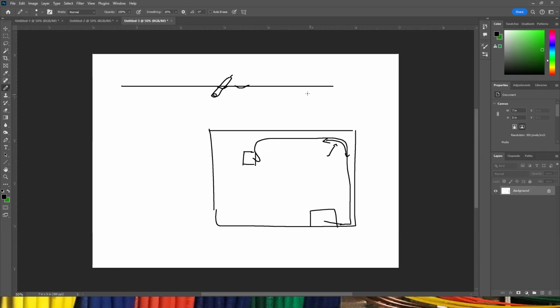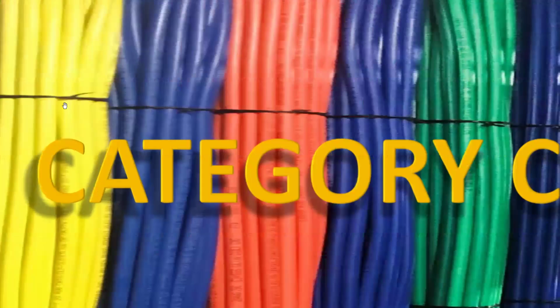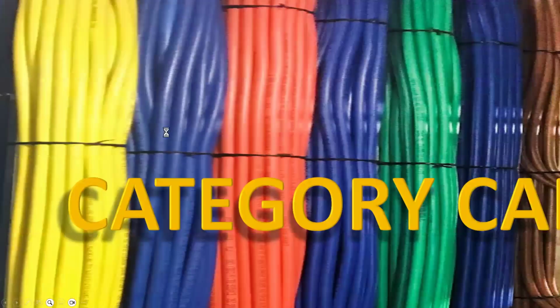Micro bends could be anything, could be a cable pressing on another cable. For example, where could I see a possibility? Oh, right here. Right in this spot right here. Yellow cables here. You see this cable here is kind of pressed by that one. Can we see other things? Right in here, this cable right there, this one is pressing on that one, creating a micro bend.